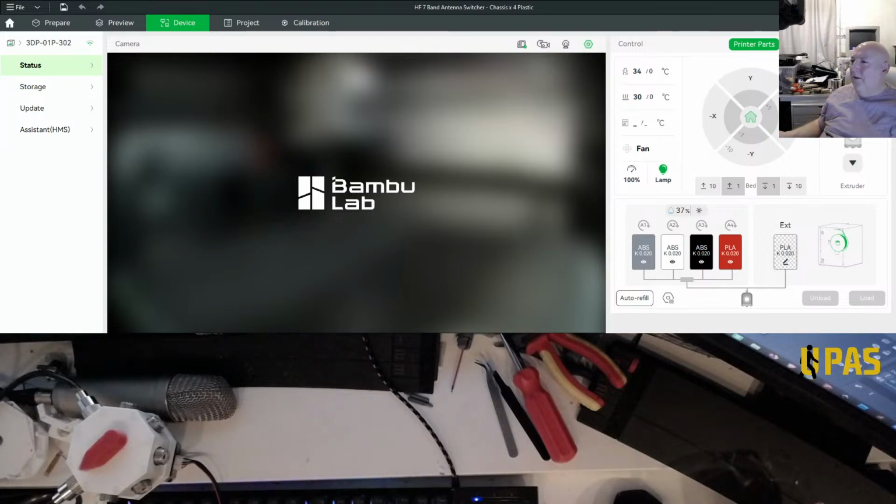Switch it away. So you could do a sweep. What I want to do is put some long wires up. Untuned long wires and some tuned aerials, verticals, horizontals, end feds, some that are just wires that go as long as you can. And if you're trying to hear someone and it's noisy, maybe you can switch to a different antenna.